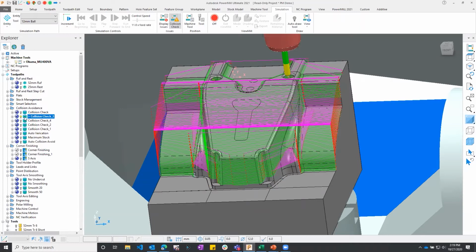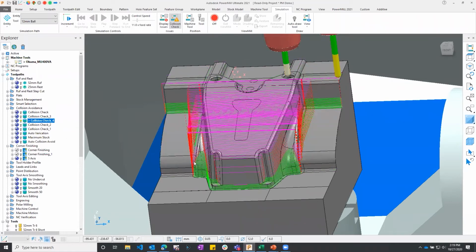Have one with more rigidity using the shorter tool, and maybe switch to another tool, or maybe start adding a tool tilt with just this one where there would have been collisions otherwise, and still use a shorter tool. So we got a few options there as far as how we want to handle that at that point. But that toolpath verification gives us a lot of options.